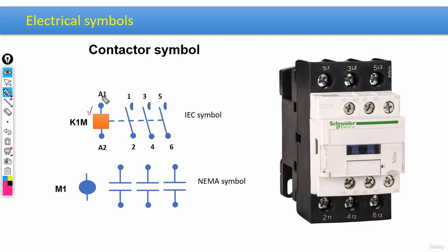One side would be connected to phase, the other one to null. And for specifying the other terminals, we actually use numbers like 1, 2, 3, 4, 5, and 6, if we are working based on IEC standards. Remember that. And these are actually the terminals that we saw before, the L terminals and T terminals.